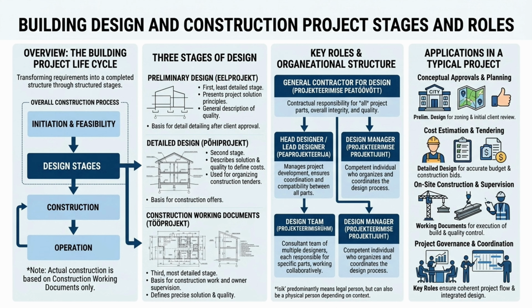The preliminary design is used mainly for zoning and initial client approvals. The detailed design allows for accurate building and preparation of construction offers. Construction actually begins only after working documents are completed, which provide the instruction for execution and quality control. Throughout the project, governance and coordination by the key roles mentioned ensures the smooth flow of work and the integrated design approach. This structured process helps transform project requirements into safe, functional and reliable complete buildings.